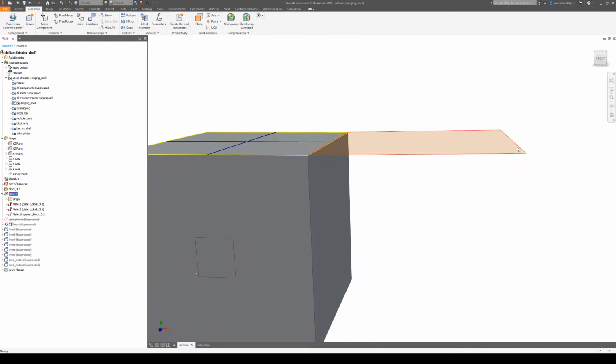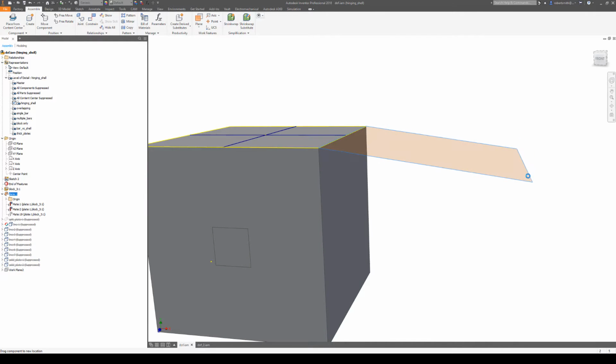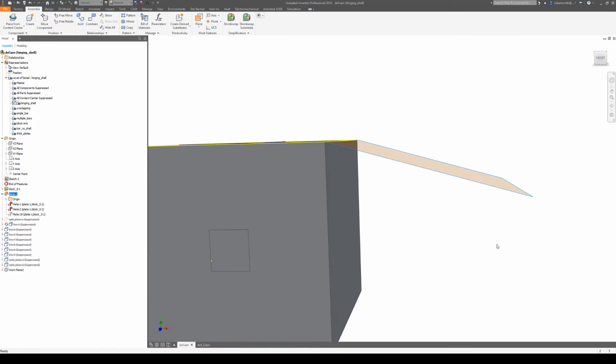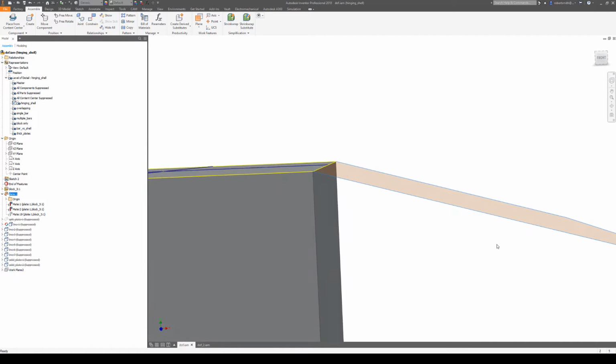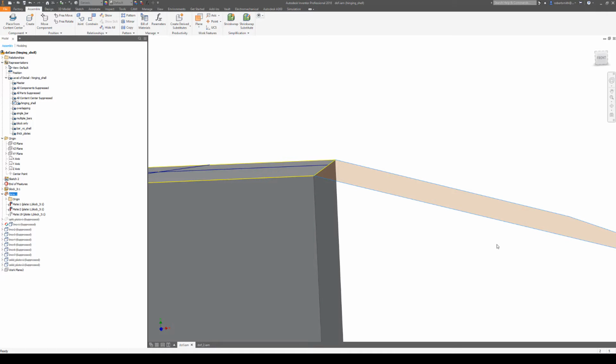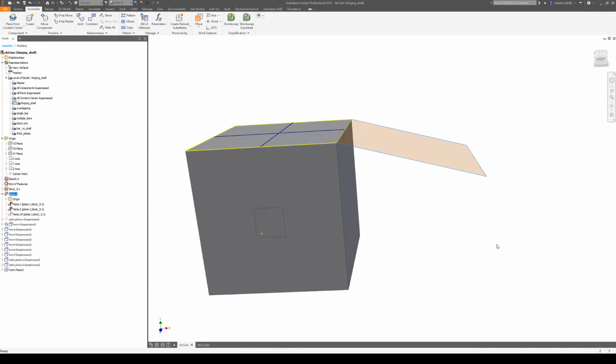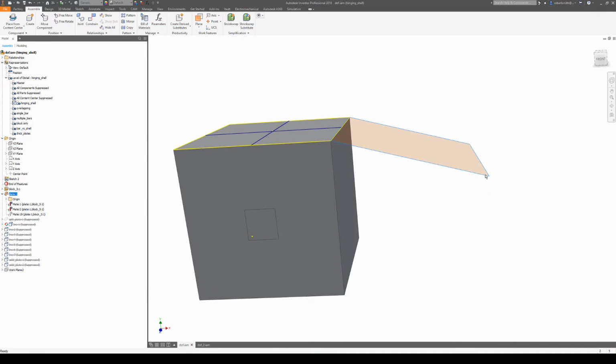Applying a force on that edge tends to push the plate down and causing rotation. I expected bending because I expected that the rotation would be resisted where the plate structure meets the solid. And that's not happening because the solid tetrahedral element does not support rotational degrees of freedom. I cannot resist the rotation that's imposed by the force I put on the end of this thing.